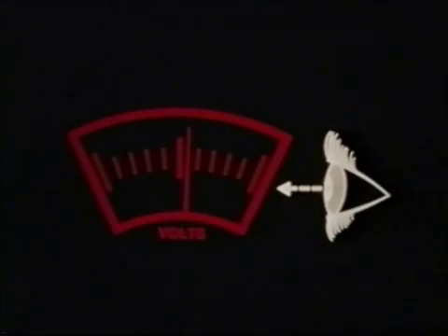Regulation of the output voltage of electromagnetic field alternators is obtained by controlling and coordinating the DC excitation supplied to the main field windings by the automatic voltage regulator. You'll remember most of these type alternators employ an external automatic voltage regulator, which senses the output voltage and compares it with the preset reference voltage.